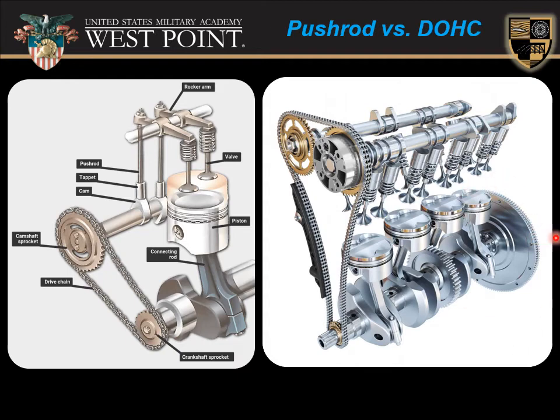The last thing I want to draw your attention to is the flywheel. The flywheel stores energy required to keep the engine turning between power strokes. Typically, there's only 1 or 2 cylinders producing power at a time, and you want that to be smooth and consistent in your vehicle. In fact, in this 4-cylinder engine, only 1 of these pistons will be producing power per stroke.